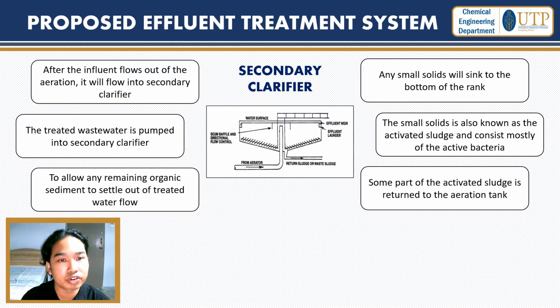After the effluent flows out of the aeration, it will flow into the secondary clarifier. The treated wastewater is pumped into the secondary clarifier from the aeration tank. The function is to allow any remaining organic sediment to settle out of the treated water flow.